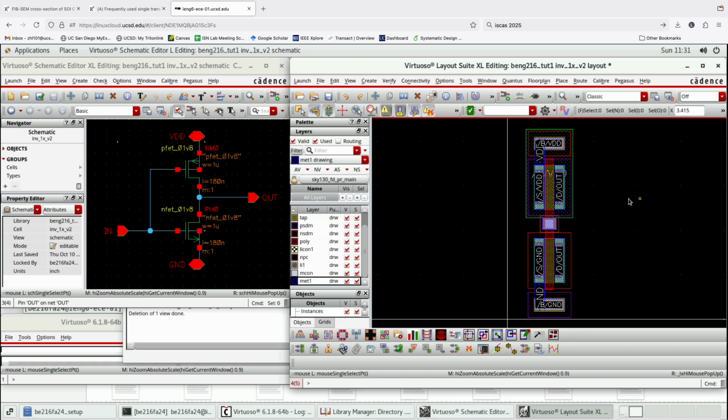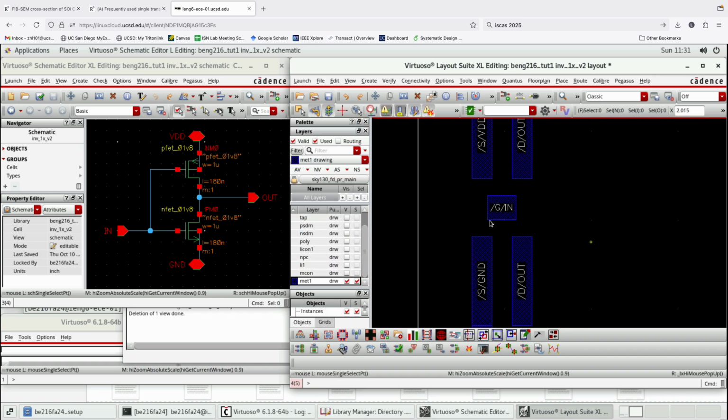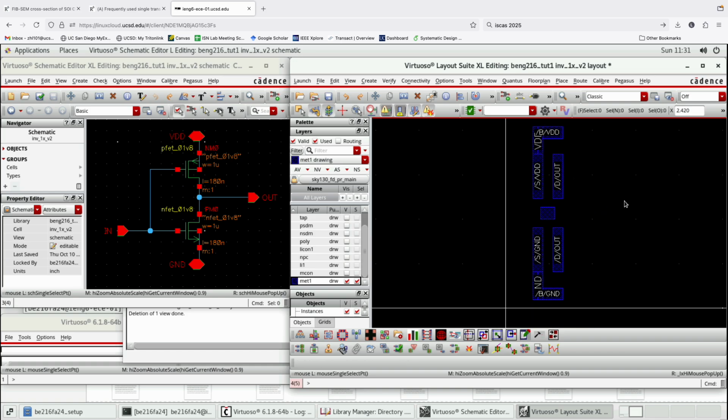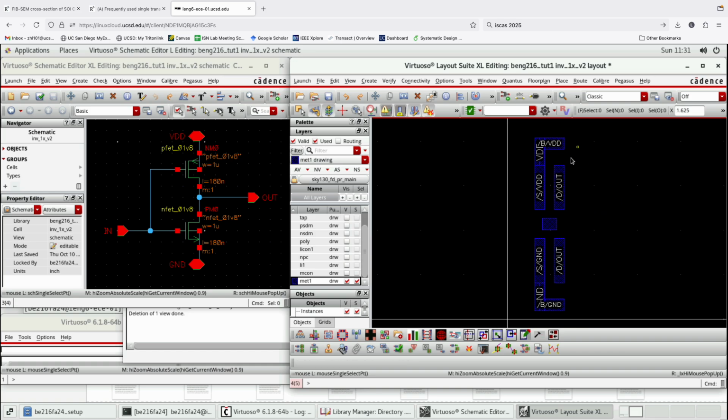What's left. So right now what we need to do is we need to connect the drain of the PMOS and the drain of this NMOS, basically this thing, right? This out net. So as you see here, if I want to do this connection on metal 1, this gate is actually on my way, right? So what I would need to do is I need to extend this metal a little bit, and then I'll route it down, right?